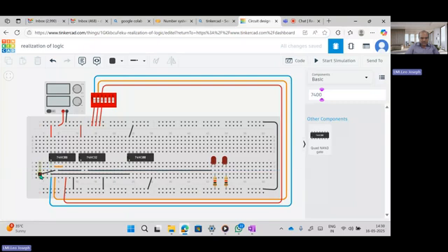Sorry, this is not coming. So I am taking here, don't get confused. Here from the second pin, I am taking and connecting with second pin. Third pin is the output, you can leave. And second and fourth pin should be shorted. So second and fourth pin should be shorted. And the fifth pin will be direct input.